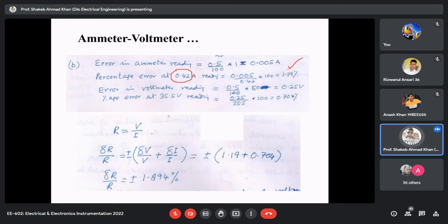तो अभी अगर आप मार्केट में कोई मीटर लेने जाएंगे और अगर वो ट्रू वैल्यू का मीटर आपको देगा, like in this situation, if the shopkeeper is giving you 0.5% of the true value and 0.5% of the full scale, obviously 0.5% of true value is more accurate meter, and the cost will also be very high. I'm telling you, there will be huge difference in cost when you will compare. So this is the meaning of these two kinds of indication of the error, the accuracy, rather, you can say.